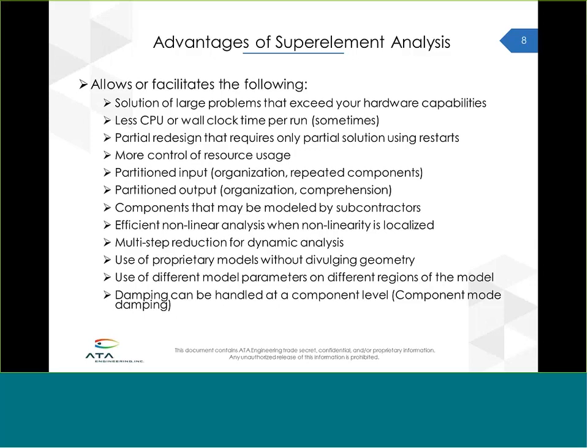Third bullet there, I don't see that one used a lot, but it can benefit quite a bit. If you have reduced portions of your model and you want to run trade studies, and the trade studies are confined to one region of the model, if you're using Nastran restarts, then Nastran can be smart enough to recognize that you have only made the change to one small part of your model, so you only have to re-reduce that part of the model. It can reuse previous portions of the model. So that can be beneficial and enable faster trade studies,